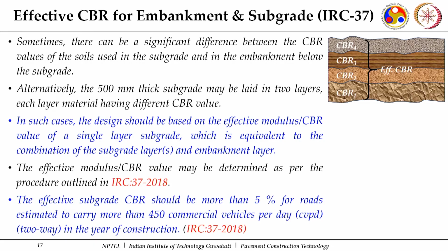Also, since I am doing my subgrade construction in multiple layers, if I am constructing a subgrade of say 50 centimeter, I will not be able to do it in one layer, I may be doing it in two to three layers.